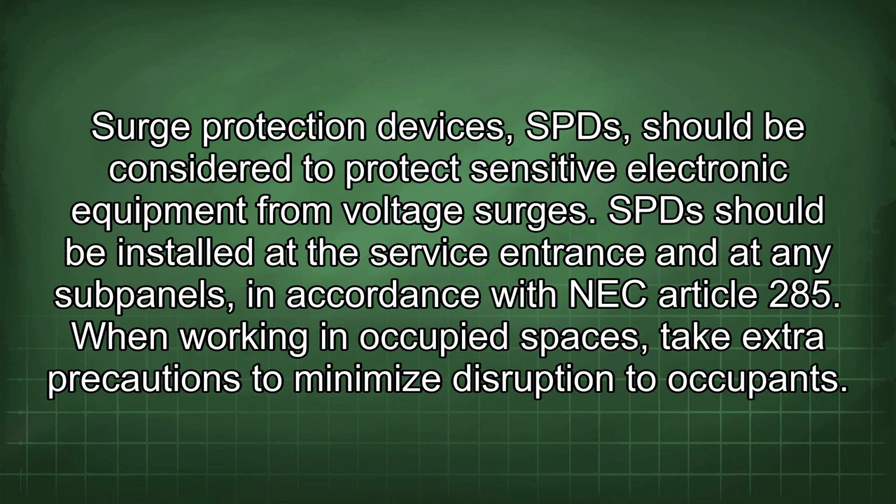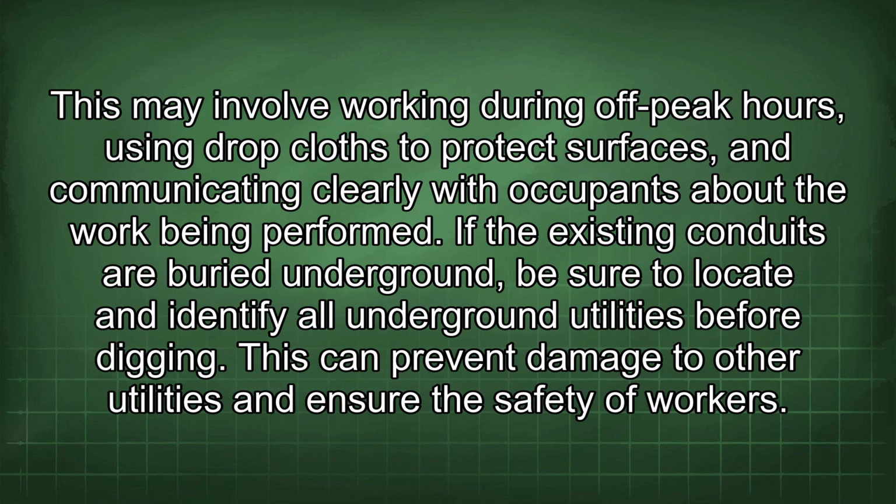Surge protection devices, SPDs, should be considered to protect sensitive electronic equipment from voltage surges. SPDs should be installed at the service entrance and at any subpanels, in accordance with NEC Article 285. When working in occupied spaces, take extra precautions to minimize disruption to occupants. This may involve working during off-peak hours, using drop cloths to protect surfaces, and communicating clearly with occupants about the work being performed. If the existing conduits are buried underground, be sure to locate and identify all underground utilities before digging. This can prevent damage to other utilities and ensure the safety of workers.